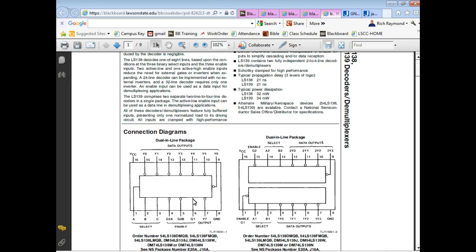These enable and disable pins were brought about by computers, microcomputers. So what happens is that everything in the computer has got an address. And then one of the buses on the microprocessor is called the address bus. What do you think the address bus is used for? It's used to select the thing that the microprocessor, or the computer, can communicate with. So the computer only communicates with one thing at a time. Whatever it wants to communicate with, it puts a binary address out on the address bus, and then we run into special chips we call decoders that actually look at the address.